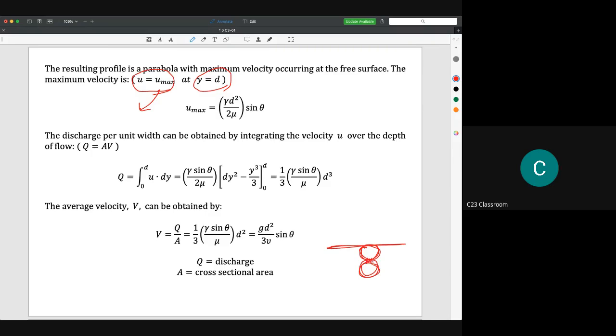The second last molecule will interact with others, liquid molecule with liquid molecule, so the shear stress is quite a bit bigger compared to the shear stress that occurs between the liquid molecule and gas. This is the air at atmospheric pressure. So the shear stress here is the weakest one, so we assume that this velocity will flow at maximum velocity.